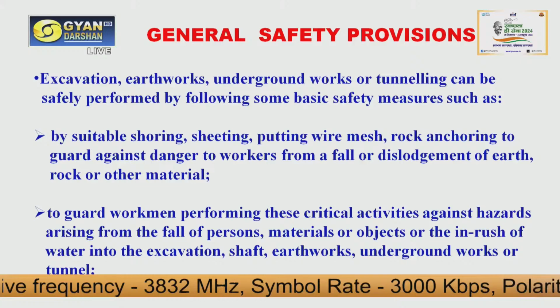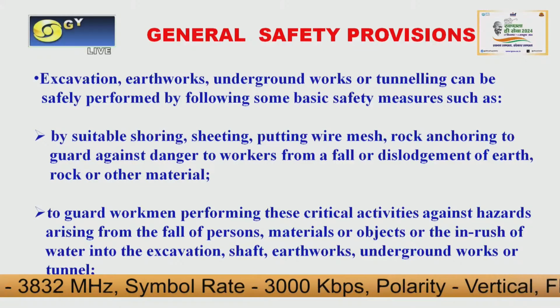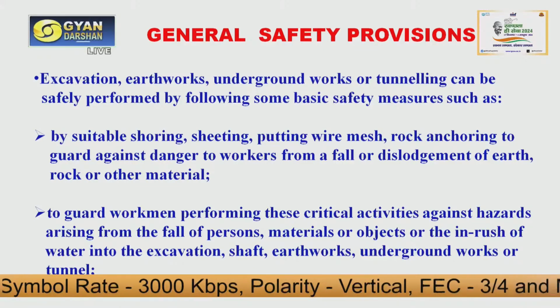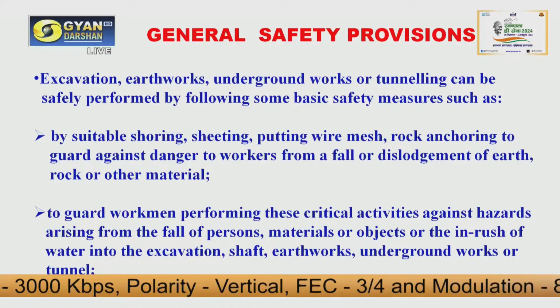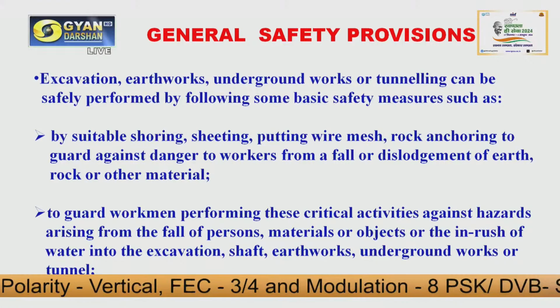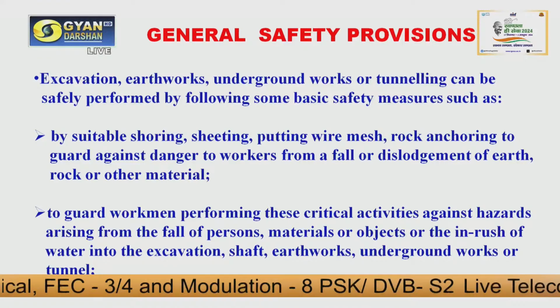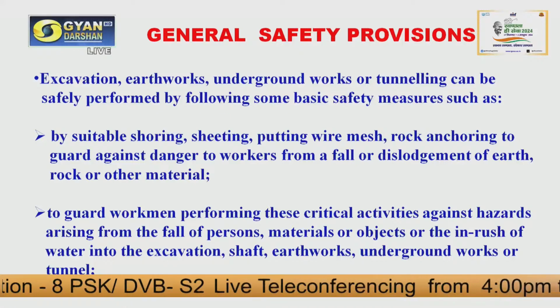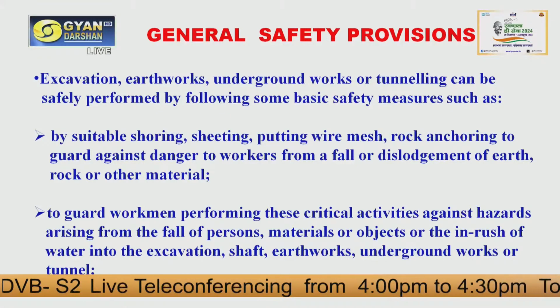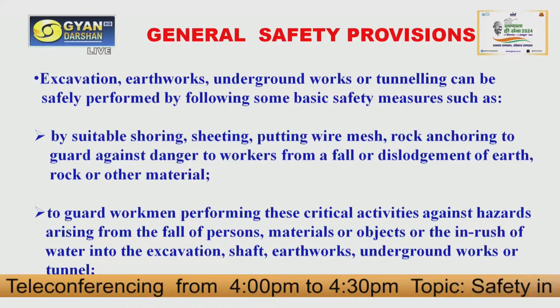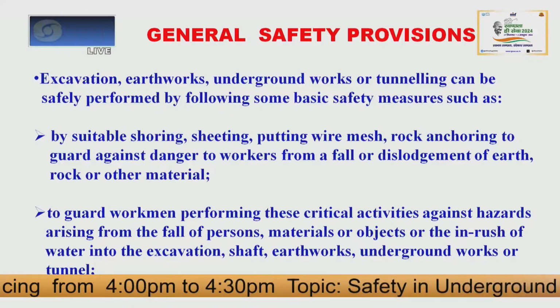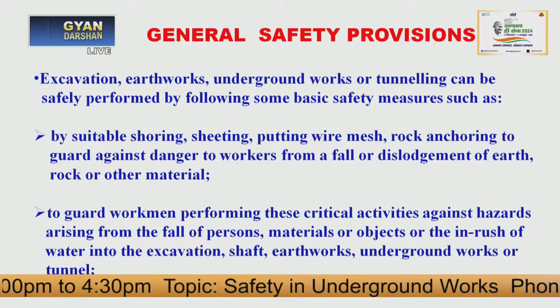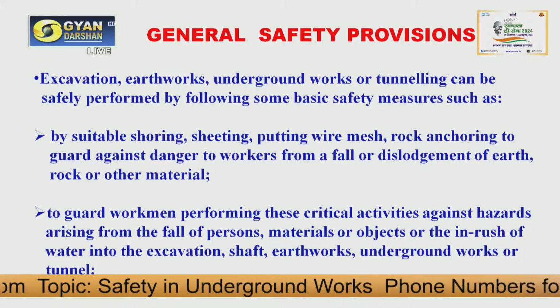If there is a possibility of dislodgement of earth, rock or other materials, then we should suitably provide shoring and sheeting, and we can also put wire mesh so that this dislodgement does not occur and does not affect our workers working there.